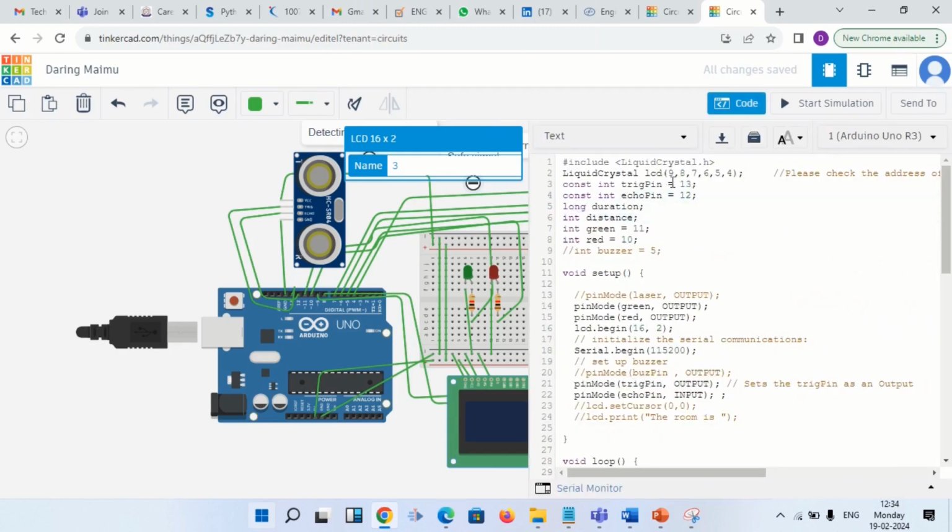For the case of the LED, one function you have to declare. So 6 pins you have to mention, whatever 6 pins you have connected with the Arduino. Okay, other pins you have connected with the logic and logic 0. This pin number you have to mention. Trigger pin and echo pin I am mentioning here. Some variables I am declaring. LED pin also I am mentioning here.